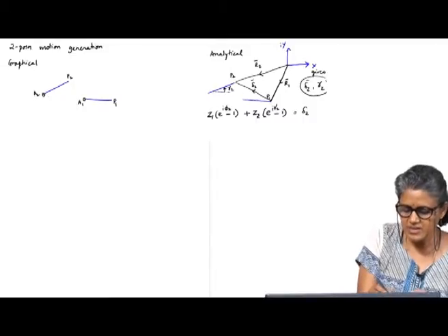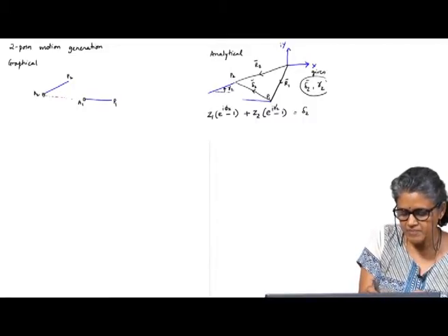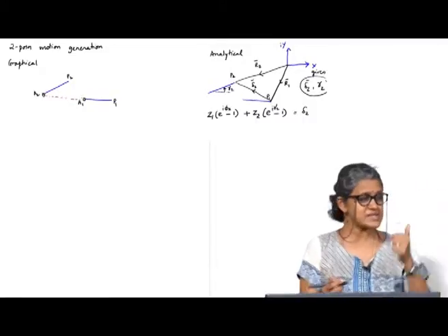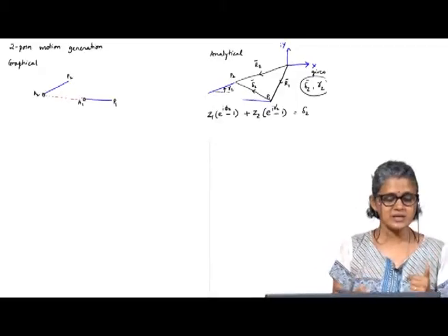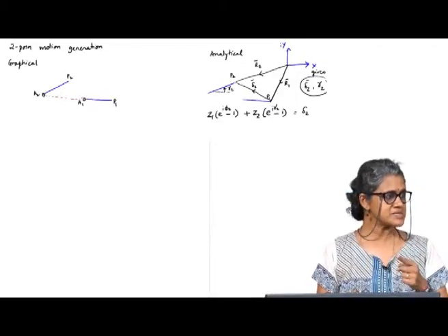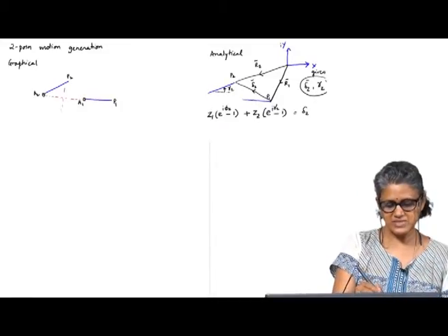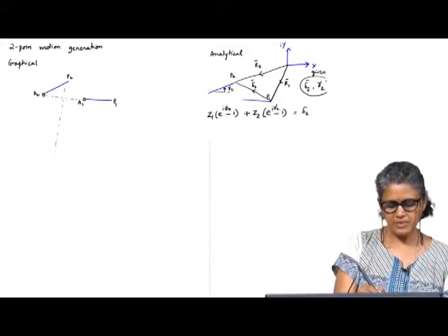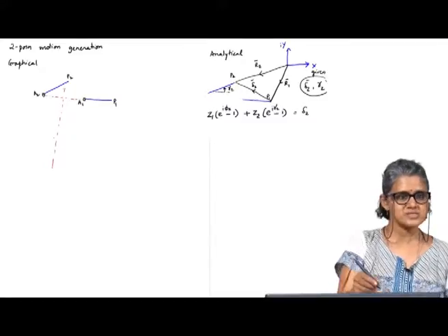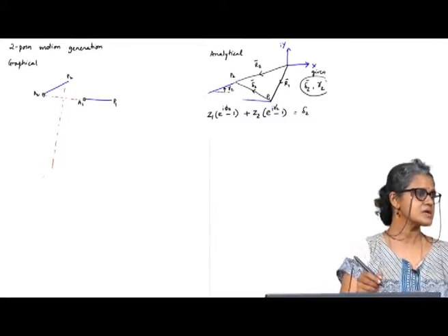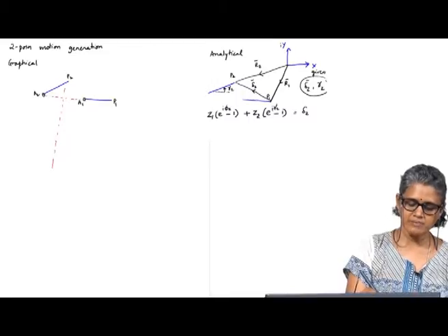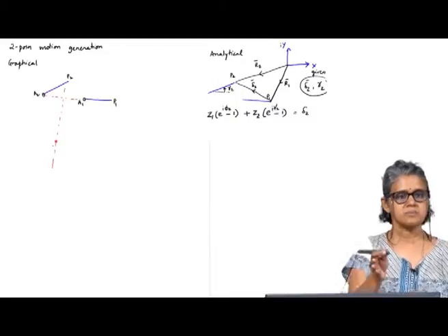I know that the corresponding center point or fixed pivot lies on the perpendicular bisector of A1 A2. So, if I construct the perpendicular bisector of A1 A2, then my third free choice is locating a point on this perpendicular bisector.